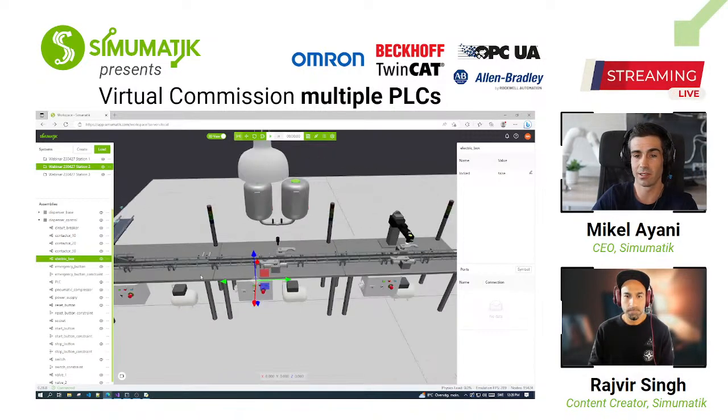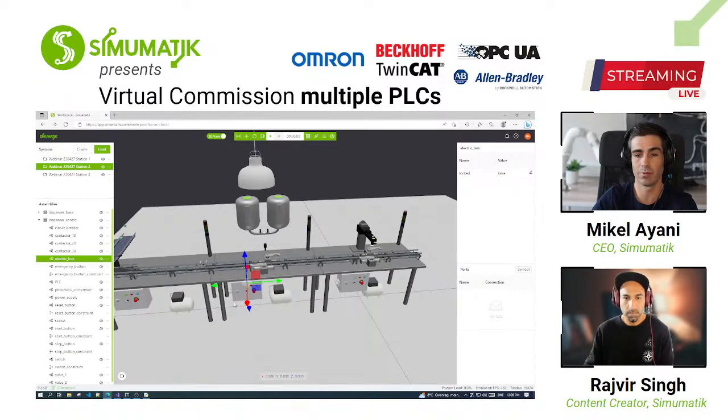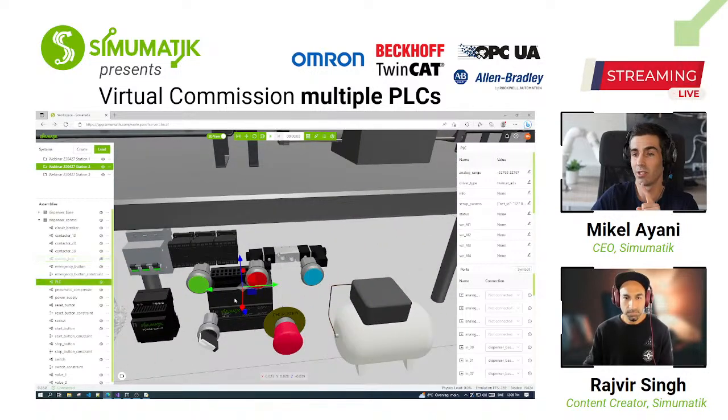So as you can see, the electrical scope or a little cabinet is the same. They all have the same PLC inside. But what I did with the second station is that I changed the driver to the TwinCAT ADS driver. This is, again, a very specific driver, just works for TwinCAT or Beckhoff PLCs, ADS.